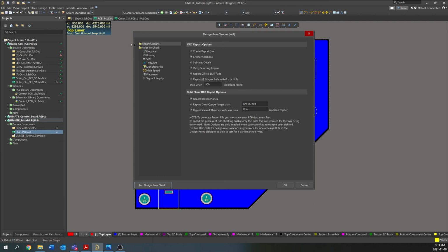And a lot of the time, your design rules are going to be based on those manufacturer tolerances that I mentioned earlier. You're going to go to the manufacturer page, whether that's JLC, PCBWay, whatever you want, and they're going to list what their tolerances are, and then you're going to add some percentage on top of that to be another margin of safety. Whatever would make sense, or what is a logical margin there, and then you can put that into your design rules, and then you're going to check your board against your design rules.